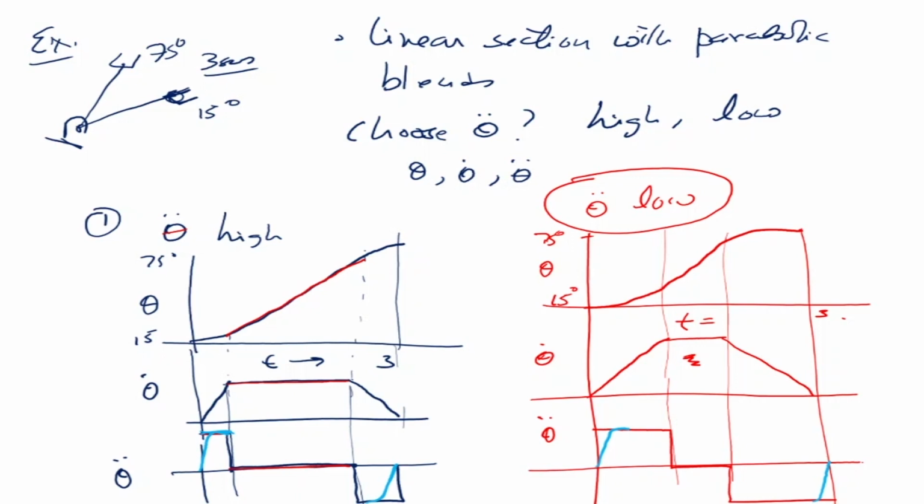That is the motor time constant, and depending on that we can choose the acceleration and then proceed with the blend section. Okay, so this is a practical way of fixing trajectories, or trajectory planning of a manipulator which is going from one position to another position.